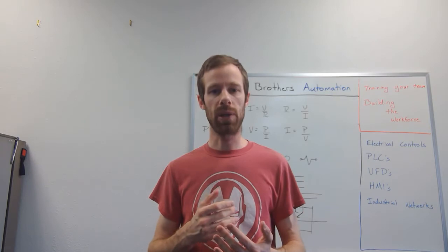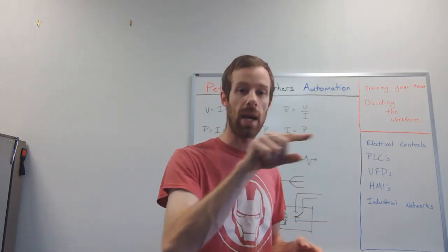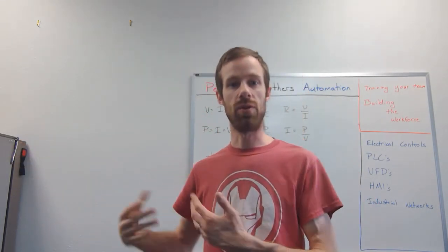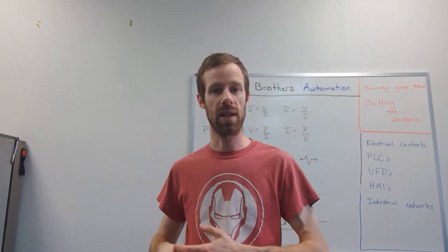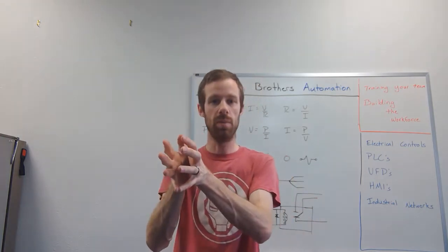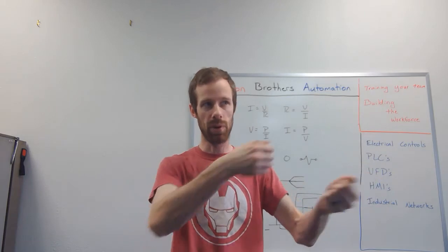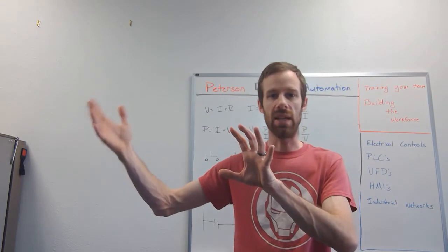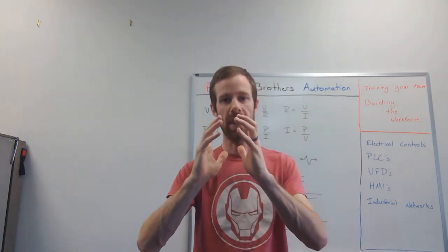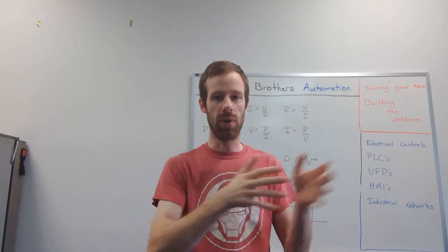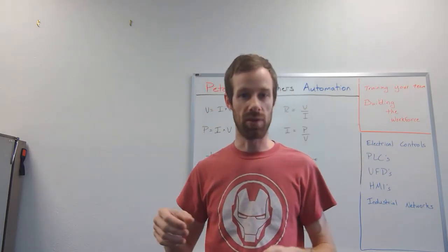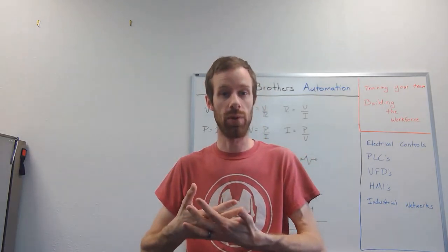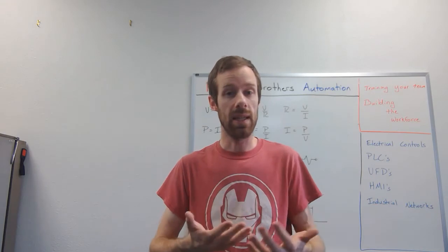It's just a little bit more complicated because we would say the load device from that push button is now the controller, but now the controller is driving a whole bunch of other load devices of its own. So the controller is just kind of this box in between all of the stuff that you push and pull and levers and sensors, and all of your final devices like the motors and lights and relays. The controller is that thing in the middle that figures out what to do with all of the inputs and then figures out how to make the output stuff do what we want it to do. But since we drive that little controller with the buttons, that means that it is the load device.